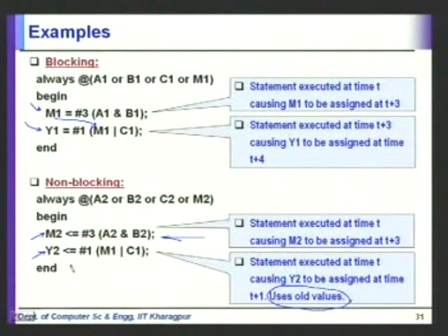So that brings us to a very interesting point: what is the sequence in which the simulator is going to do this? What is the scheduling semantics of Verilog? Think of a set of modules, some having always blocks, some being structural, etc. At every point of time, we have certain events which are active, in other words, those events can be executed now because nothing blocks us from executing them. And there will be some events which are blocked against hash delays, maybe hash 5 a equal to b, so that's blocked against the hash 5. And there will be some events blocked on at-the-rate constructs, so at the rate of a, but a hasn't changed yet, so it is waiting. The statements which follow that are still not ready to be executed.